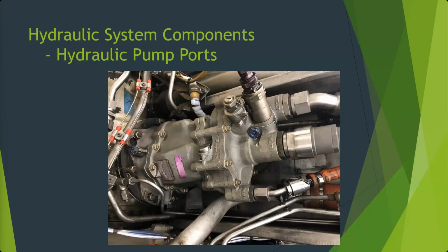So the body of the pump here, I'm going to set this down, hopefully everyone can see well enough. In this area right here is where we have the swash plate, the pistons, the piston block, all that stuff. Over here, this section, they were talking about the compensator spring that controls the swash plate, how tight it is. That's this piece right here. On ours, you can loosen the nut up and then turn it to adjust.